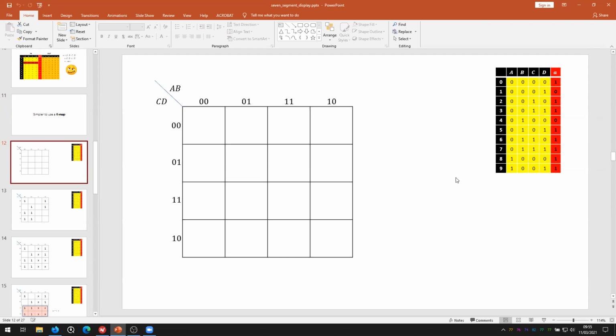The only thing I'd say is that probably what most people do in this case is they extend this to all 16 inputs, and then update this table to handle the letters A, B, C, D, E, F, because you can do that on this digit display as well. And that's one way of getting around it. It's probably the most efficient way, really. But in general, how to handle don't cares, there are various ways.